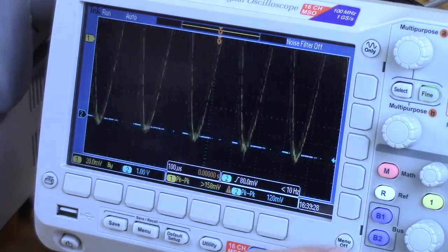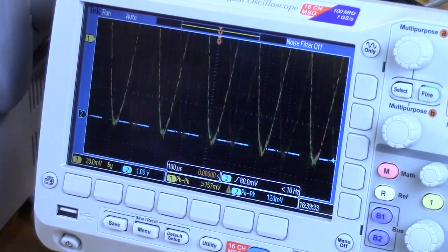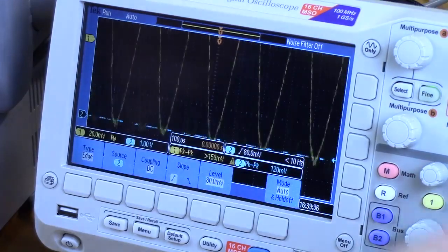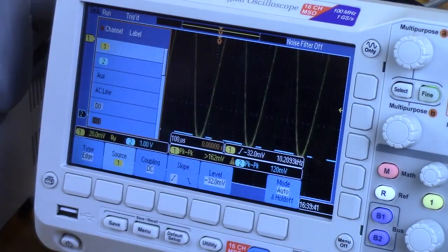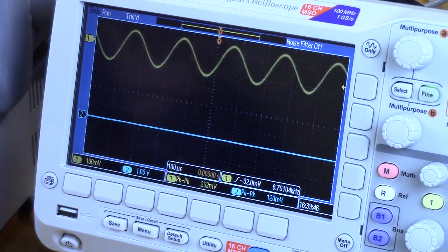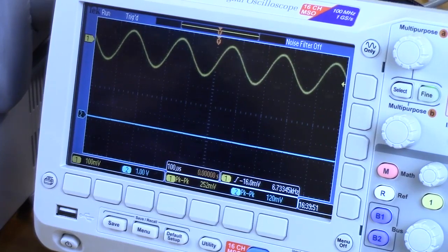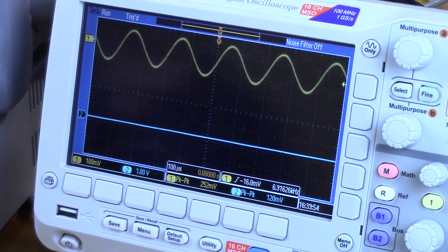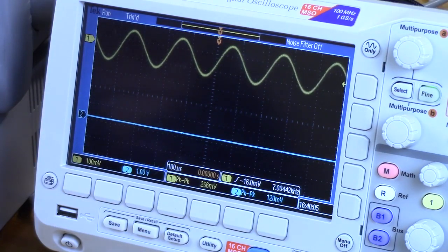Okay, so we now have a wave, but it's not triggering on it particularly well. So now let us set the trigger 1. And now at least it's holding still. But it's still not real happy, but that's okay. We have a pretty high gain, so the input's going to have to be small. So what we'll do now is let's set our DC operating point and get it to 1 milliamp. Right now there's no output, but that's probably because the R2 is not set correctly. The transistor is not biased correctly.